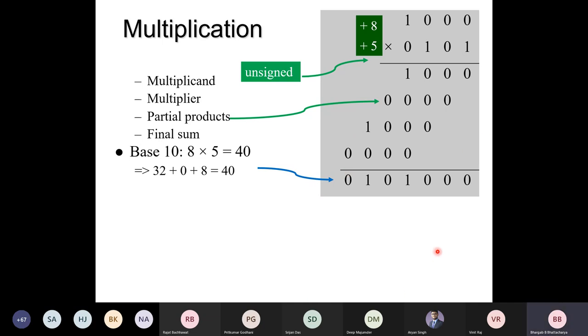That's why you now see a more important purpose of the carry save addition. So all we need is an array of AND gates to create the partial products, and then some sort of carry save addition to produce the sum. Done.